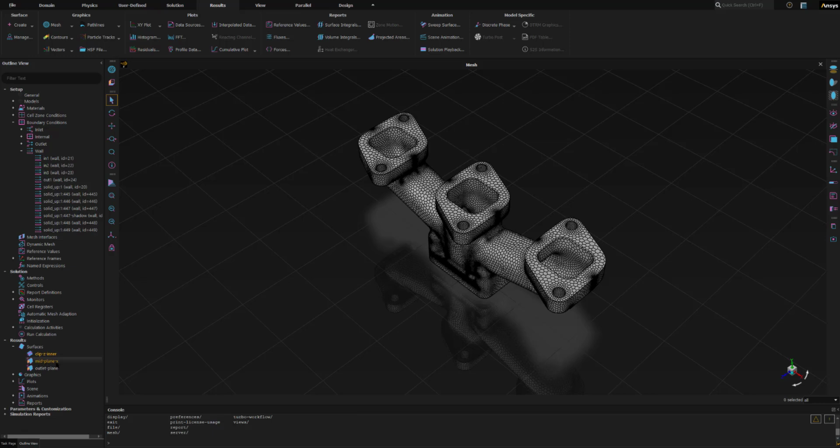One in the Z coordinate, one in the middle X plane, and one here in the outlet plane at the bottom in the Y coordinate. So based on these new surfaces, I will go and show how we can generate our contours. For the first contour, I will display field contours of temperature on the mid plane and also on the outlet. So let's see.